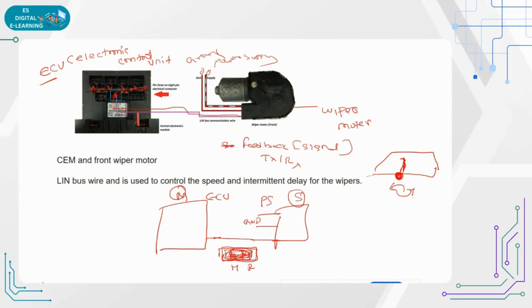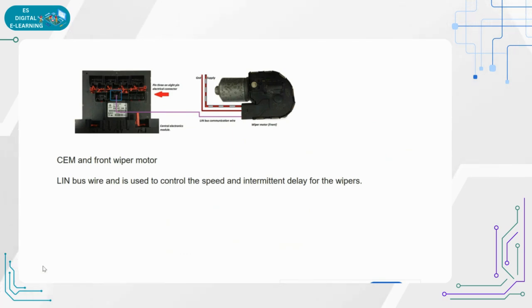Okay, good. So I hope that is better. Someone actively responding is required. And this is a wire, this is how we are communicating with the wire. Even in interviews, if they ask how you have the ECU and how you are connecting the motor, what pins it has, you need to explain that we have the power supply, the ground and the LIN wire. It is just an understanding of the LIN protocol in real time, how we are connecting.